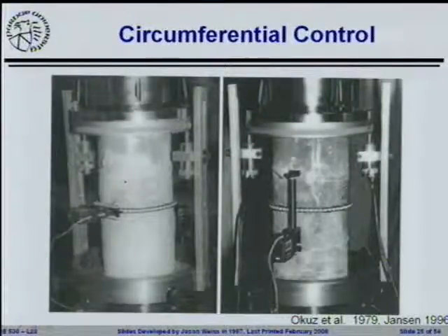One of the things that happens inside of concrete is that it starts to crack. Once it starts cracking, we don't necessarily have this same concept of Poisson's ratio. Poisson's ratio is still there, but after it starts cracking, it takes on a different meaning, because what you're actually going to see is the material experiencing quite a bit of lateral expansion because the cracks are forming straight up and down.